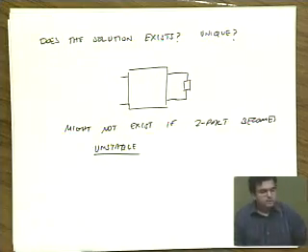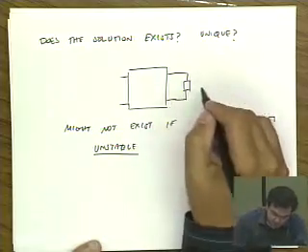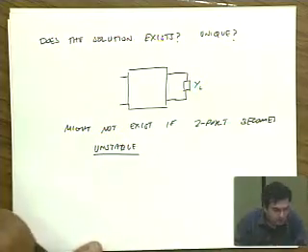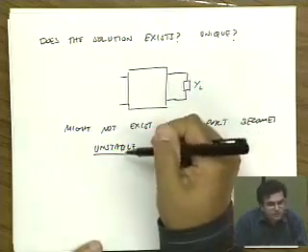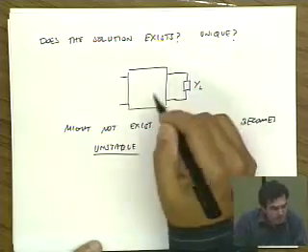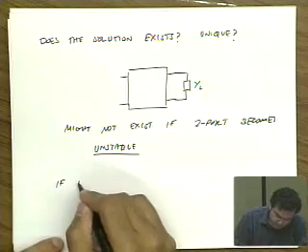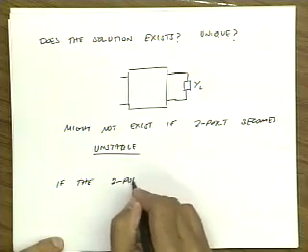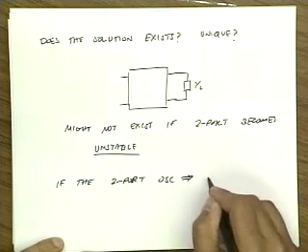We haven't really talked about stability at this point, but just intuitively, if I present a certain YL here that causes the output to oscillate, then clearly this solution for maximizing the power gain, the transducer gain, does not exist. In fact, if the two-port oscillates, that implies infinite power gain.